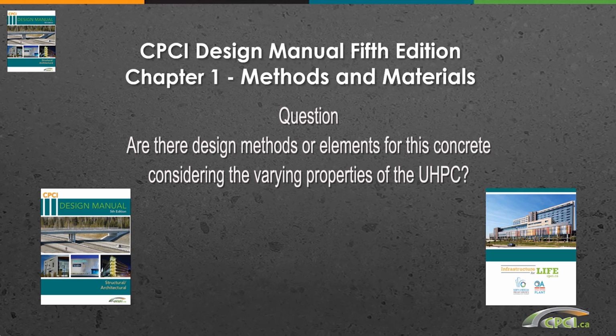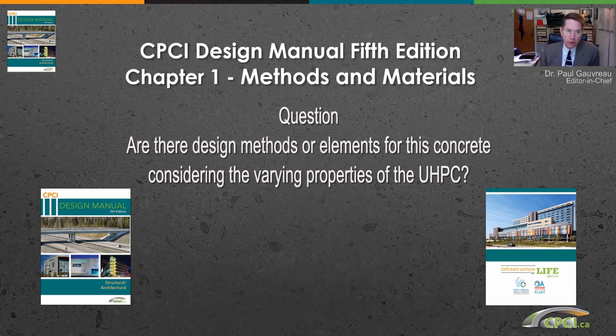That's correct, Rob. You mentioned in your part of the presentation that for the A23.1 standard, there would be an annex related to a material standard for UHPC as a material. And in CSA standard S6, the Canadian Highway Bridge Design Code, in parallel, there's a task force that will be working on a non-mandatory annex with suitable design provisions for structural elements constructed of UHPC.